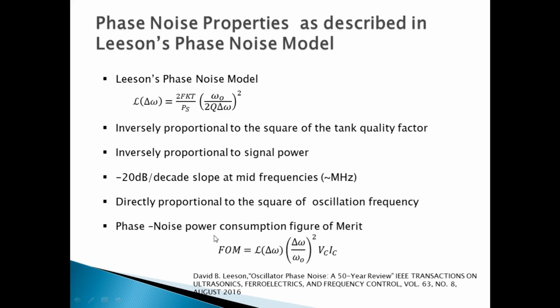Now coming to the figure of merit, it compares the phase noise at a particular distance. So here is the figure of merit. You can have a look at it. For every oscillator, away from the carrier frequency, the phase noise becomes smaller. Of course, the phase noise is much larger near the carrier, and as you move away from the carrier, the phase noise goes lower.